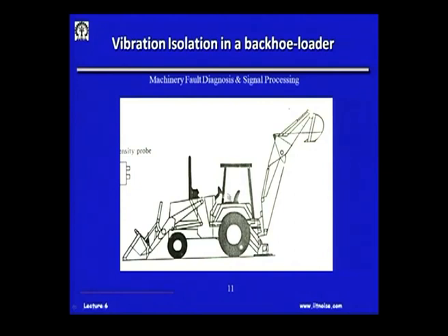These cabins may look very robust, but they are actually supported on 4 mounts, and again our vibration isolators come into play there, and one has to decide on a good amount of vibration isolators. This is one example. We are talking about, say, a truck.